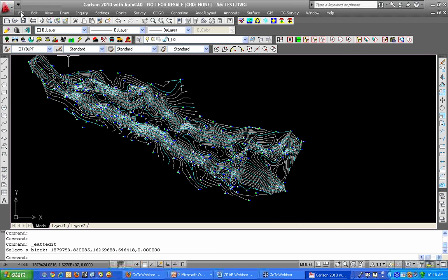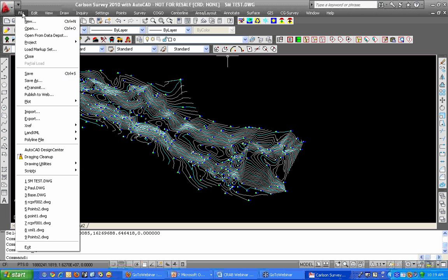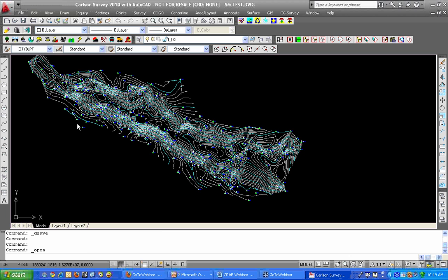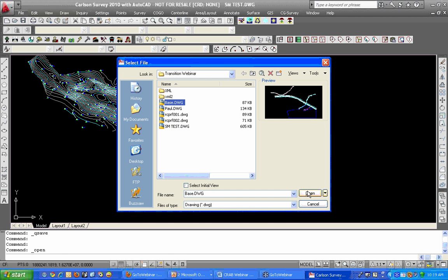Other things that you will want to be able to convert. You're going to want to deal with your centerline files. Well, the good news is both LandDesktop and EaglePoint use polylines to create their center lines. And so we can simply use those polylines to generate a Carlson centerline file. We'll open up another drawing here.